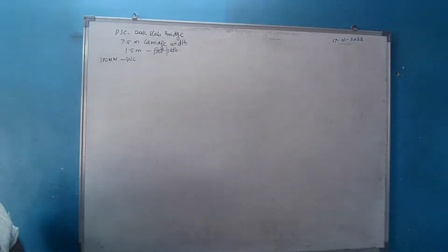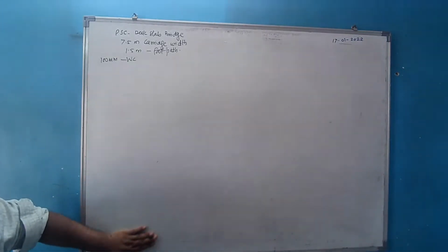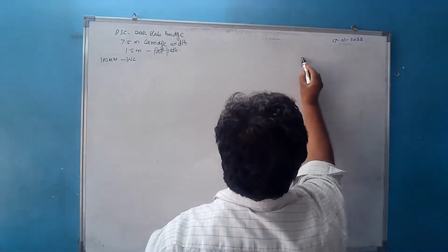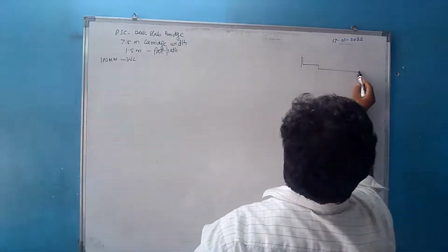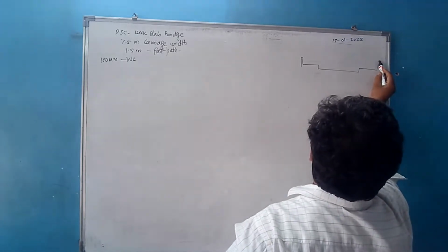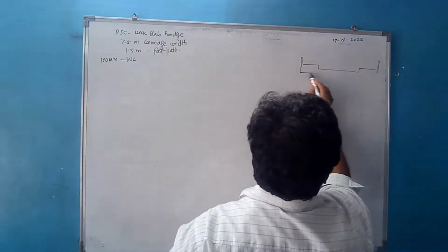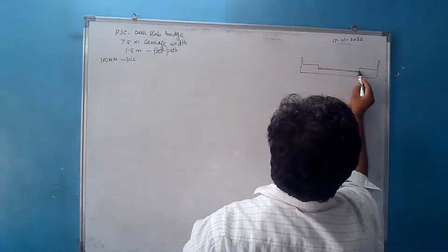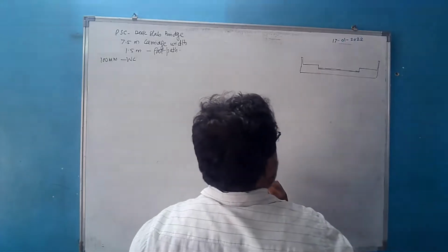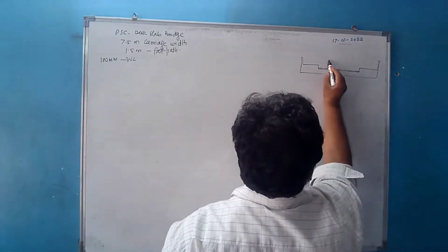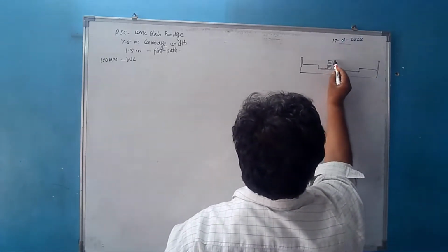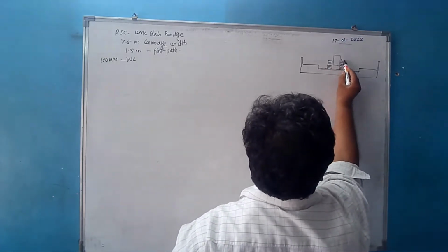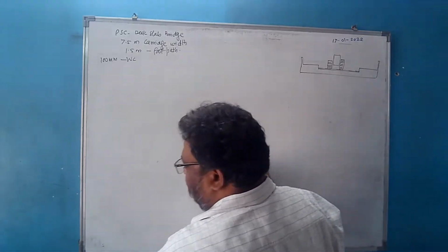As we were supposed to design this, before going for the design, we had to analyze it. If you will see, this is how the cross section of that bridge will be. There is a wearing coat of 100 mm and the kerb was 300 mm above this. And the load acting was IRC class AA tracked vehicle. There are different types of vehicles.